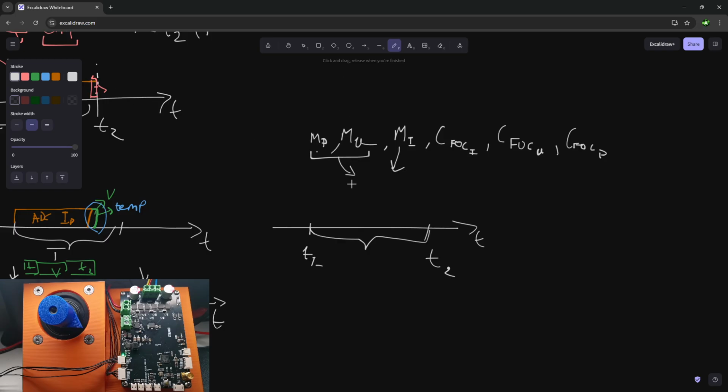So how we want this to work is we want to finish these three as close to the end of the period as we can. We have this as a target. The reason for this is very simple: the closer we are to the end of the period when we calculate, the fresher the measurements, and the closer to the actual values on the motor we will have when we update control systems.